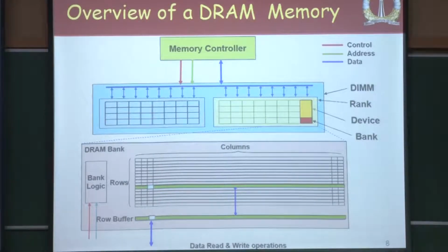Inside. Okay, means if you are talking about these row decoders and column decoders, they are all inside the device. Suppose I have some address, the address will point to a channel, then into a rank, bank, row, column. Correct. So, some level of decoding happens. Well, you can actually say all of this goes on the channel, then appropriate decoding happens inside that. Others will actually ignore those signals.